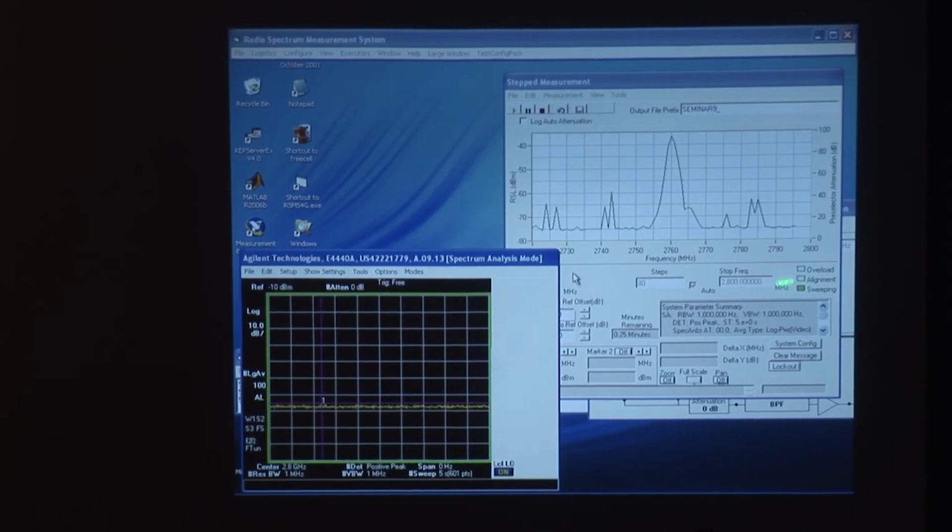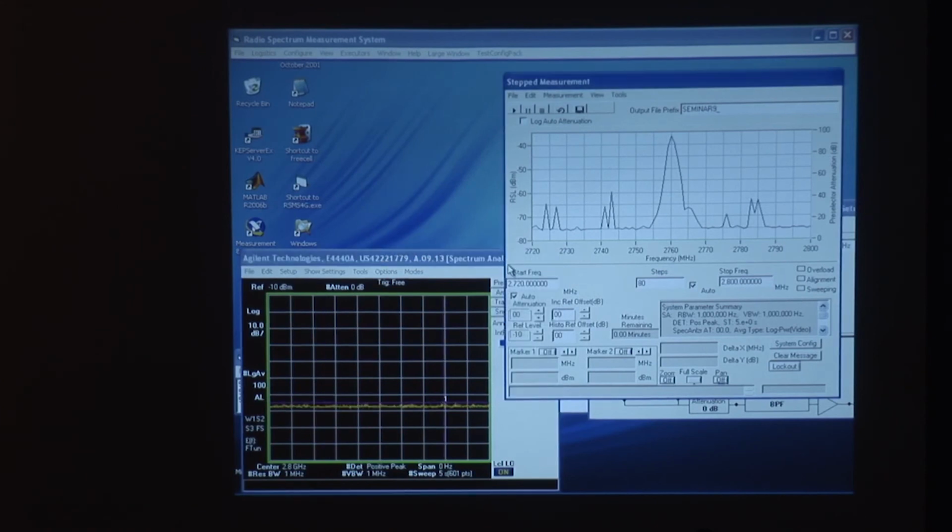So it sweeps for 5 seconds, pulls off the maximum point in 5 seconds, corrects the point for calibration, plots, it steps to the next frequency, and runs across the frequency range designated in frequency step sizes that are just equal to the bandwidth that we're using. In this case, 1 megahertz bandwidth equals 1 megahertz step sizes, and now we're finished with this particular demonstration radar measurement.